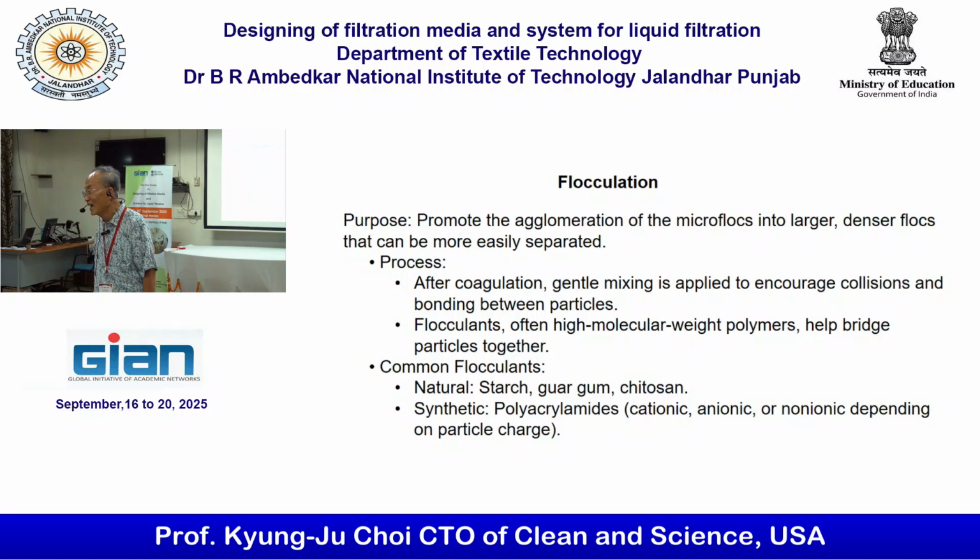She has found that coagulation is a chemical process, flocculation is physical. Oh, a physical process. Coagulants are added, so there is a chemical reaction. Here polymers are added, only increasing the size of the particle. So no chemical reaction. Wow, that's a good answer. That is really great.